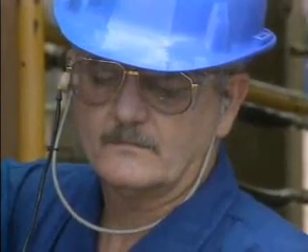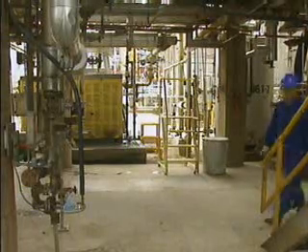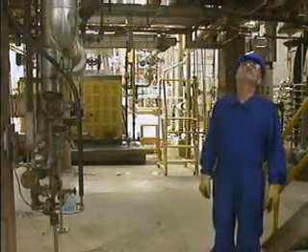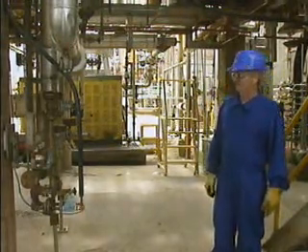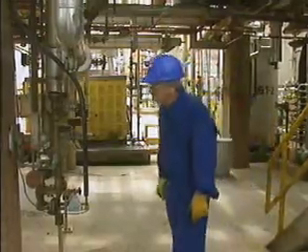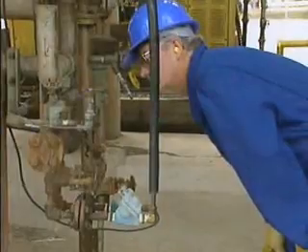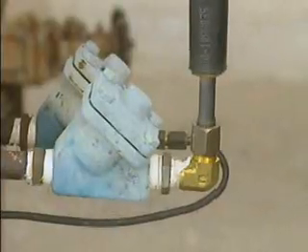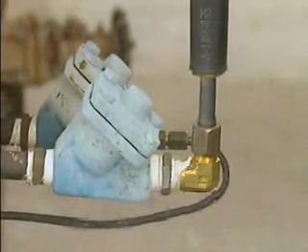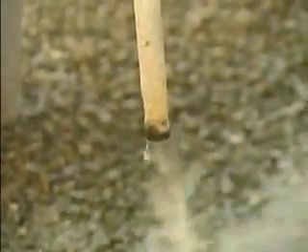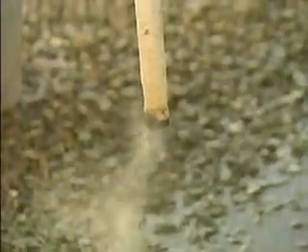A visual inspection can be a very informative part of a steam trap survey. But as with other types of inspections, you need training and practice to be able to perform the inspection effectively. Begin by simply looking over the trap for condensate or steam leaks. Leaks typically occur at piping connections and at the steam trap's body-to-bonnet connections. Next, see if live steam is being discharged from the trap. This is relatively easy to determine if the trap discharges to the atmosphere.